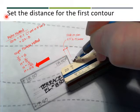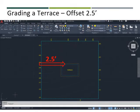2.5 feet. In AutoCAD, the math is exactly the same, but the way that we determine 2.5 feet in AutoCAD is simply to use the offset command. So we can take our terrace outline and we can offset 2.5 feet, and it will give us a line around the terrace that is exactly 2.5 feet away from the edge.